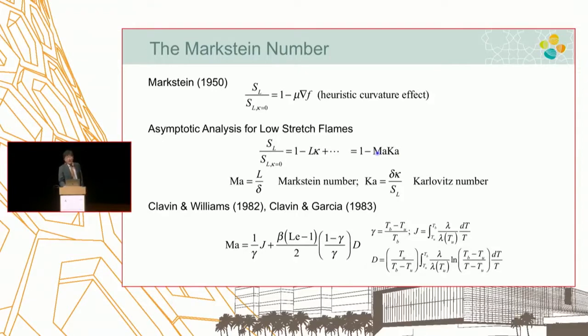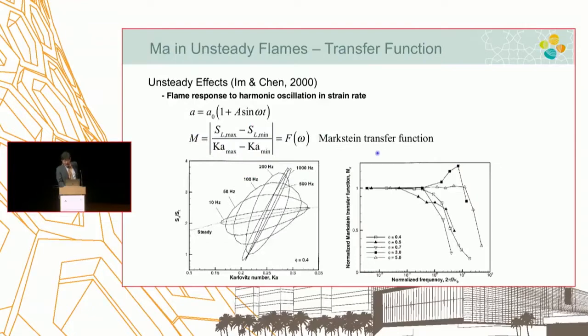Well, this is a kind of quasi-steady context. If you have flame, but a lot of the flow field is unsteady, and this flow field itself has its own time scale. If that time scale oscillates very rapidly, often exceeds the frequency of the flame to respond, then flame acts like a low-pass filter.